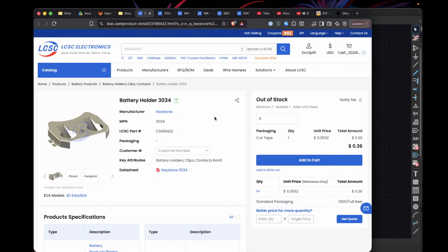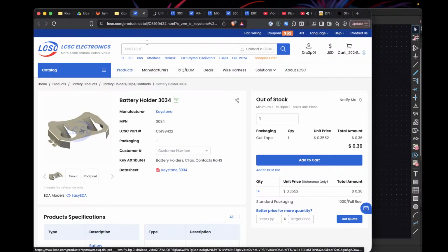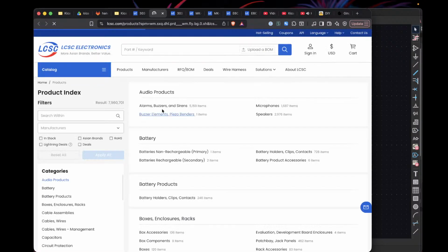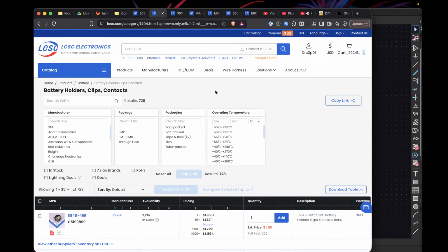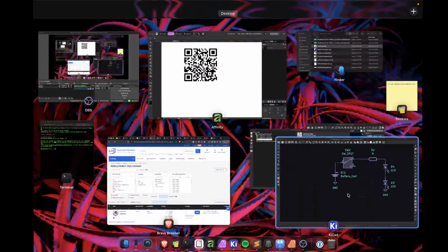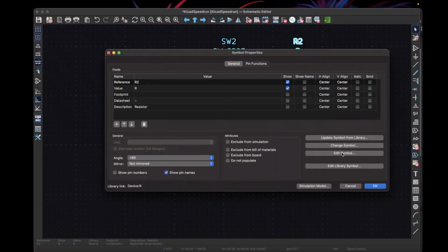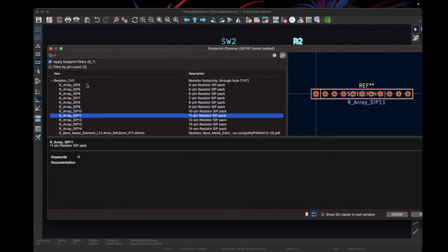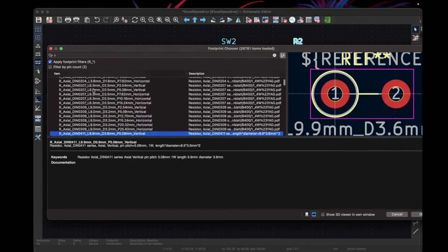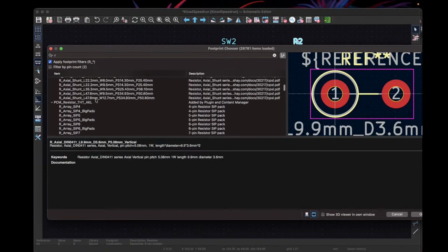If you're just getting started, even Mouser and DigiKey and stuff like that, it's just an insane catalog of parts to dig through, and it can be really annoying. KiCad has a set standard which comes built into the footprints in the list, so you don't have to go find or make stuff. Not for everything, but they do have a standard, but I'll show you why this is also kind of a thing. So I'm going to click on the footprint, I'll just edit that one individually. We're just doing R. THT is through hole, and you can see there are a bajillion resistors to choose from.